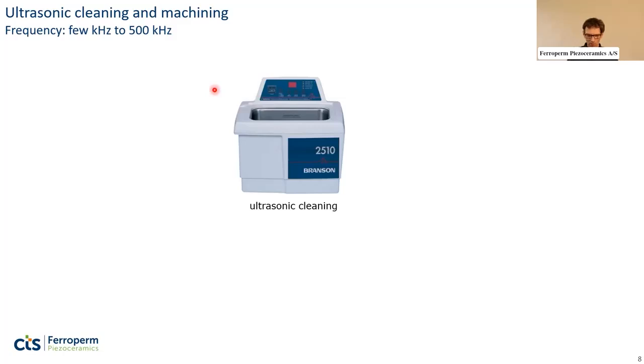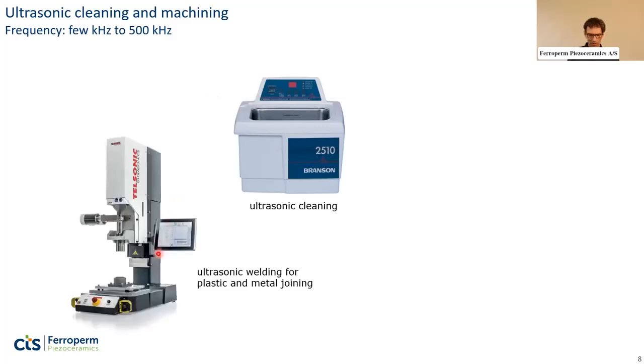Okay, so another example here, sort of in the same corner, is the ultrasonic machining, where you can use ultrasonic welding. If you want to join 2 pieces of plastic or 2 pieces of metal, it's a very efficient way of getting a very quick joining just by rubbing 2 pieces of material together, and then you'll get a softening or even local melting just in the friction zone.